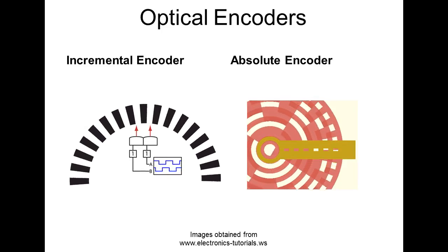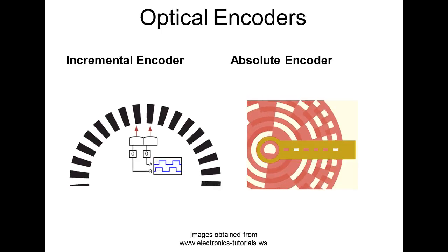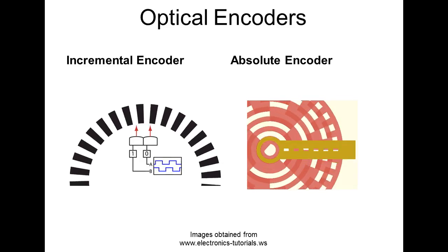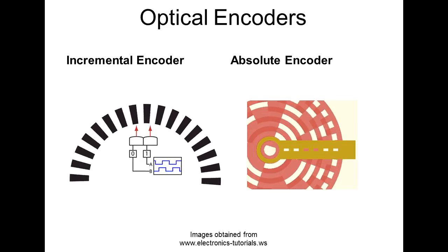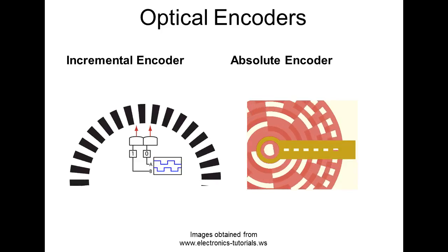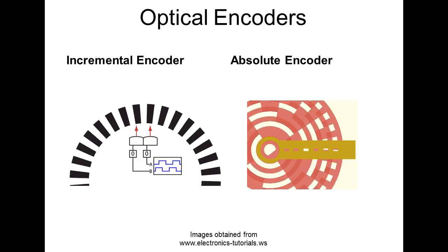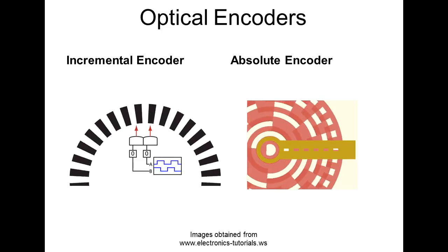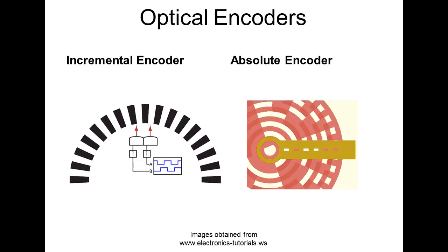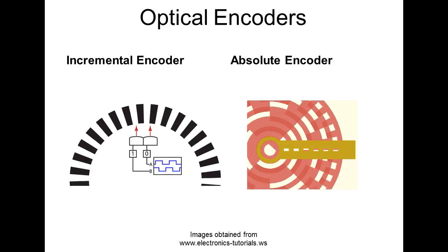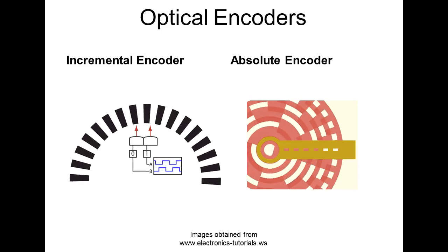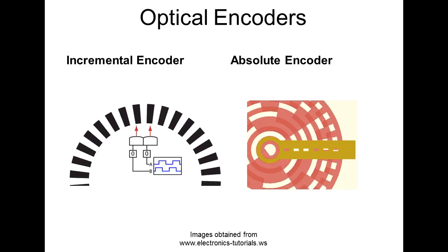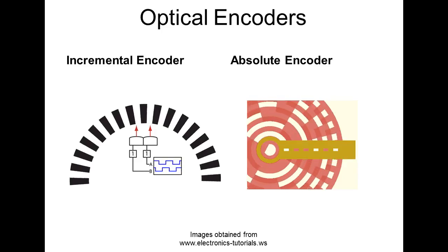So these are digital, and what's nice about digital position sensors is what? We don't have to send them through an A to D converter. We can bring these directly into a computer or the controller of our robot without going through an A to D converter. And they just use those offset sensors on the incremental encoder to give us a direction.